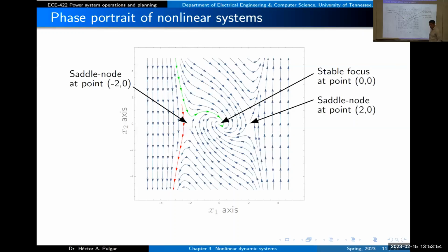Yeah, I mentioned last class that the nonlinearity can come from the generators, or it can come from the load itself. As you said, if we assume that the load is constant power, that will make the power flow equations quadratic in form. But if you assume another characteristic, then the load might behave in a different, nonquadratic, nonlinear fashion as well.